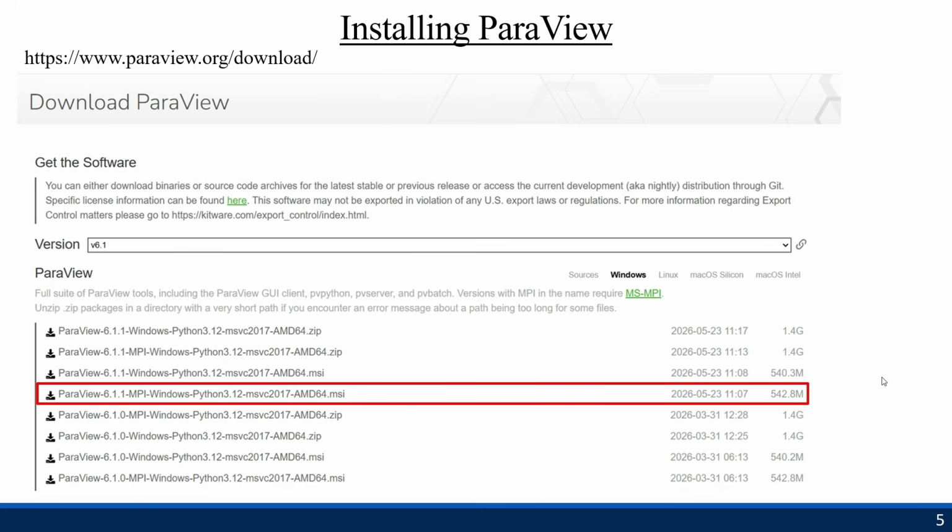And just one thing I want to mention: when you go into using ParaView off screen, you want to make sure your client version locally is the same version as the one on the module you loaded on the HPC. Sometimes you might have to re-download a slightly older version of ParaView, because if the version doesn't match, then ParaView off screen won't work properly.